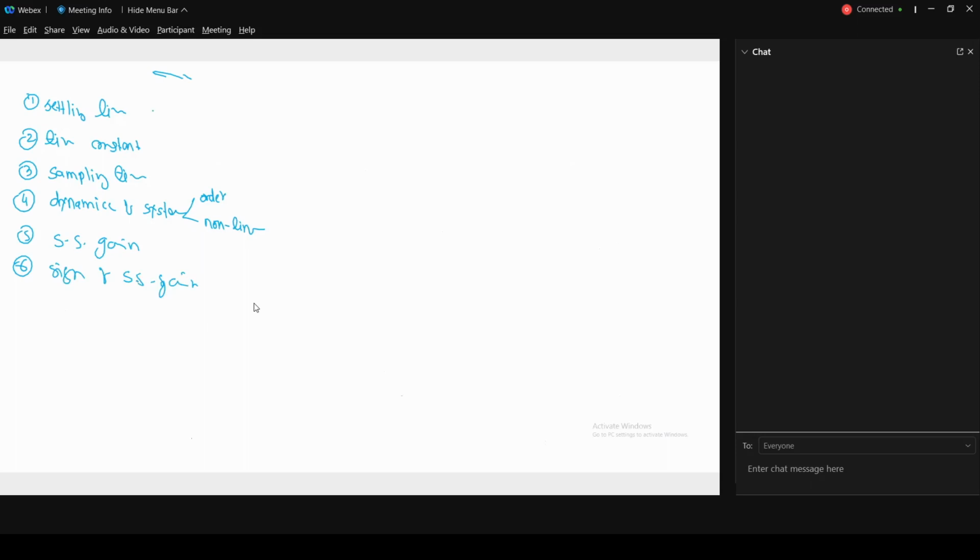Okay, so we understood settling time is when the response comes within plus minus 5% of the ultimate value. Correct. So when we give the step change, the ultimate value is where the system doesn't change after that step change. The height of the system doesn't change and stays there.